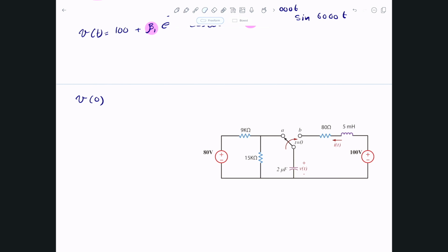So here's the circuit before switching, and just to highlight a few things in here. Hopefully you'll get that I0 is just simply 0 actually, because there's no current flowing through this, because the circuit here is cut, okay? And just to emphasize, this is t equals 0 minus, right before switching. Okay, and of course what we have as well is the following. So this part in here is just simply an open circuit.